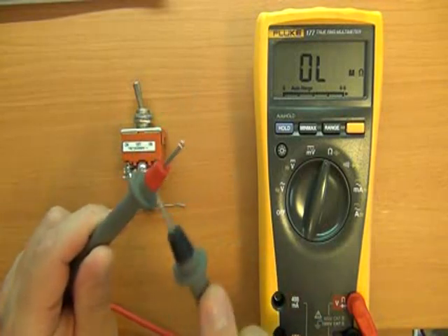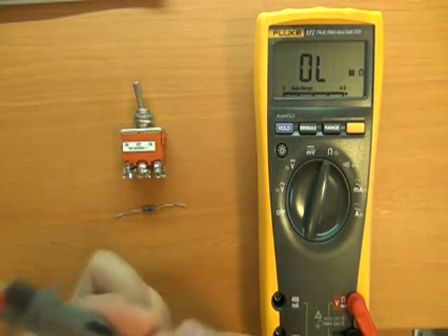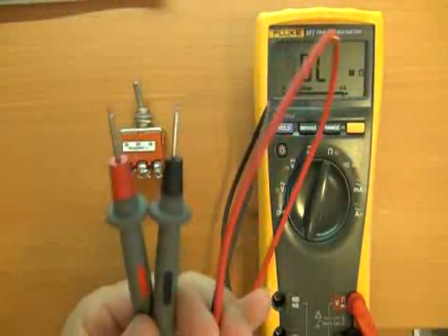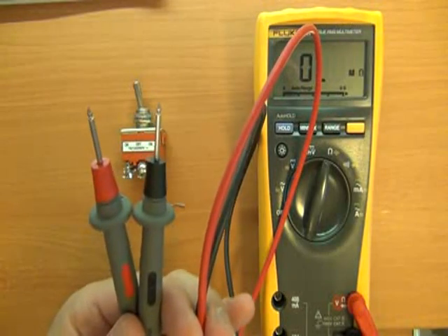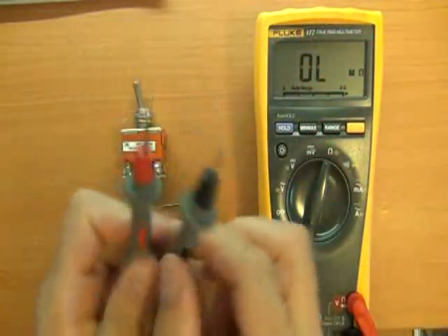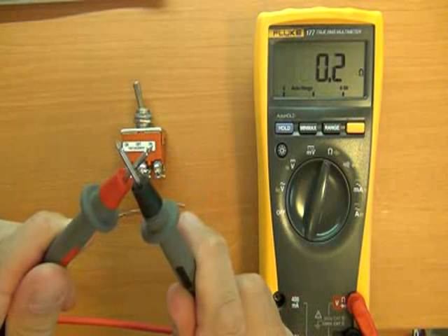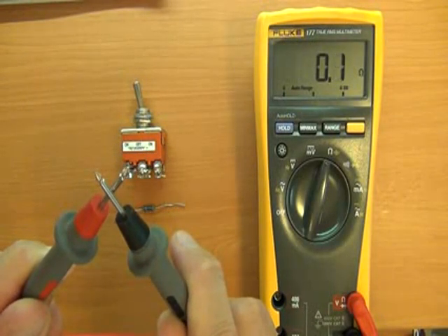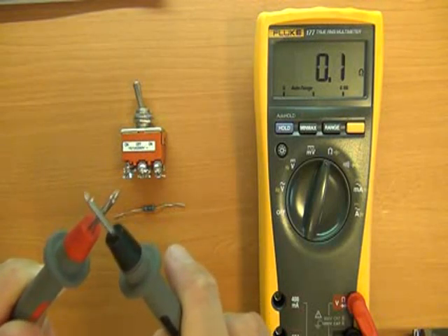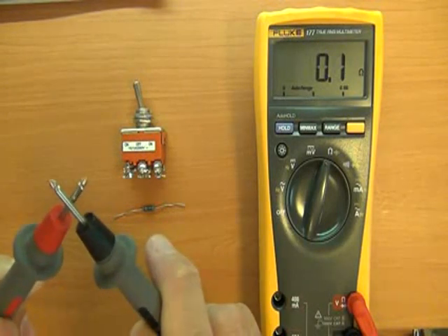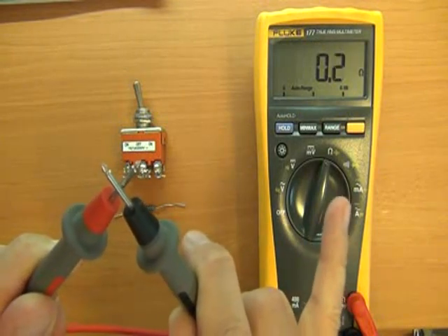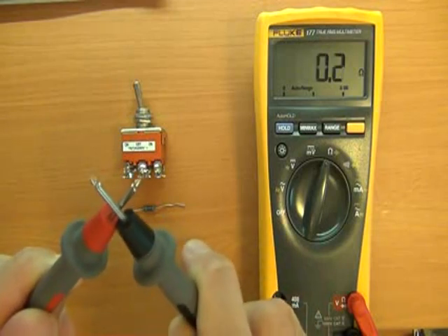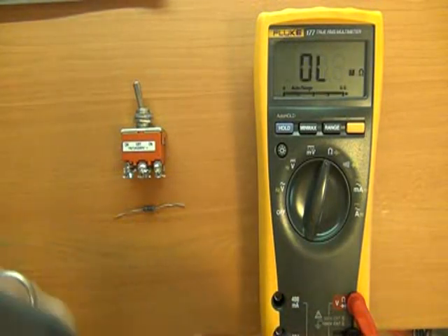Now then, one interesting test and something to note is that even your multimeter leads can have resistance which can affect your reading. So what you can do is put your probes together and just note, as you can see there, there's even 0.1 or 0.2 of an ohm resistance in these leads. Now, there's a couple of things there. There's either potentially calibration or accuracy of your multimeter, or that literally is the resistance in your leads.